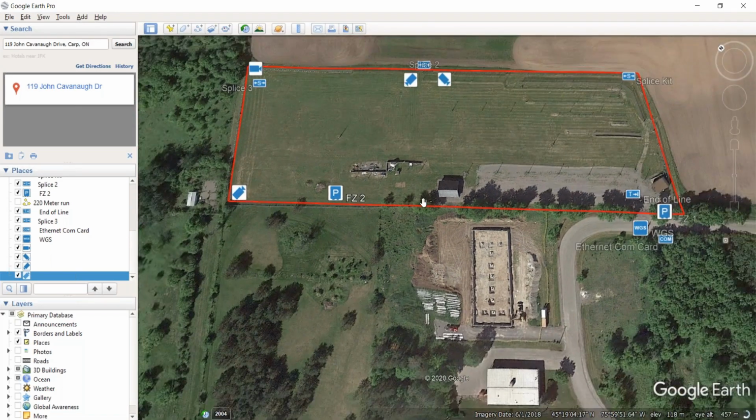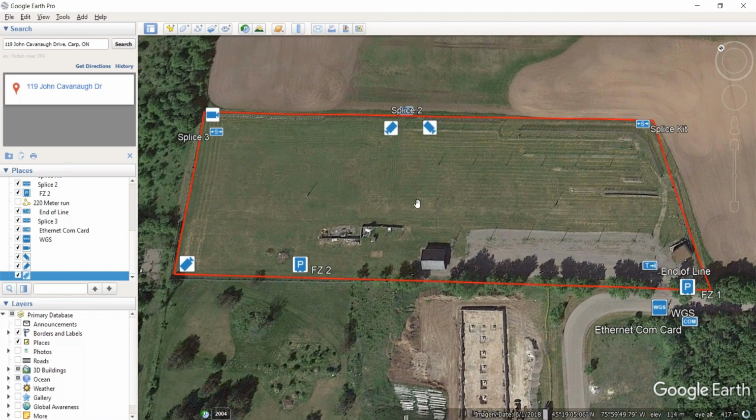Now, one of the things that we do at Senstar when we design any system is we always add 20% cable overages, and that's for a couple factors. Number one, we would go through more cable at the gates, and that would be at the corners, sorry, and that would be the same if we were actually running Ethernet. If we were in conduit, we were trenched underground. Every time we bend, we lose a bit. Again, with gates, we have to go up them and then underneath them, and that's the same with a pedestrian gate. And luckily here, we managed to save the meters that we would have used here by using a terminator, but we see that we need that.